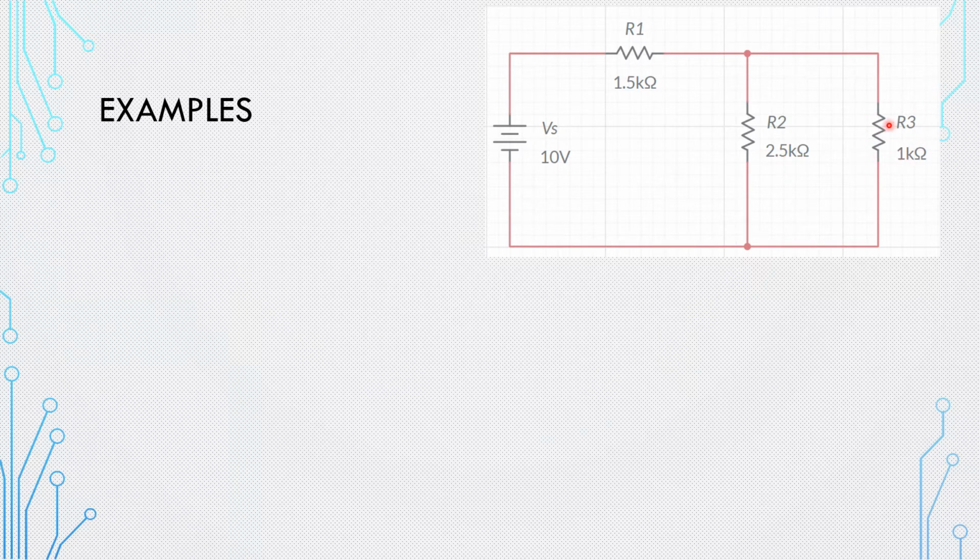You can see that they are in parallel. So if I know the voltage across V2 or the voltage across V3, then they're gonna have the same voltage. But V2 and V3 do not have the voltage value of the voltage source, since they are not connected in parallel with the voltage source. So be careful with that, put it in mind once you try to calculate.